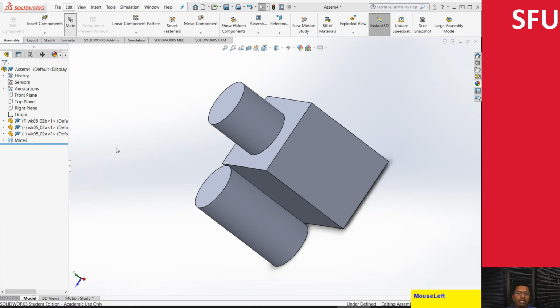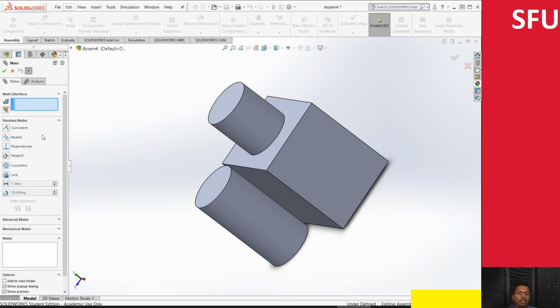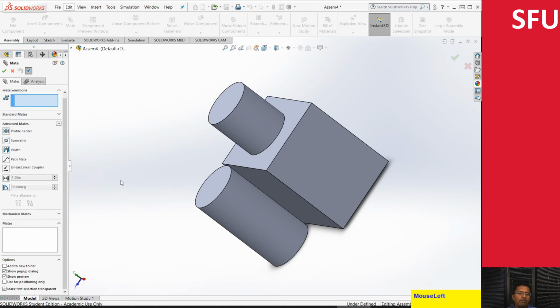So you get the standard mates here, and then you also have advanced mates: profile center, symmetric, a width constraint, which will be between two centers, or we can do a path mate, linear coupler, and a distance or an angle over here.